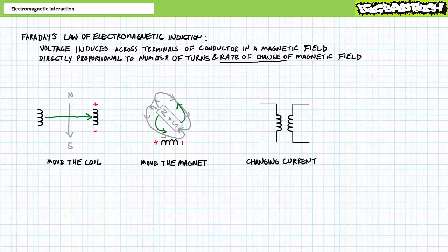As an alternate method, one could also forego the process of physical movement altogether and employ changing current, as is commonly available in AC systems. Consider two stationary coils in close physical proximity. If current through one coil started sinusoidally oscillating back and forth, the associated magnetic field in the first coil would expand and contract as a function of current magnitude and direction.